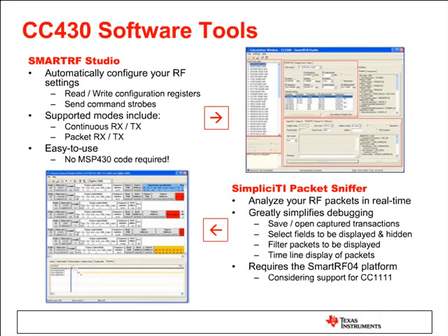It's also kind of a cool tool if you want to use it for evaluating your RF front end. Let's say that you design your own CC430 board and you actually just want to see what RSSI you get at certain distances. You can do this all automatically without writing any piece of code. So SmartRF Studio, remember it, use it, and use it along with the EVM tool that I just showed you.